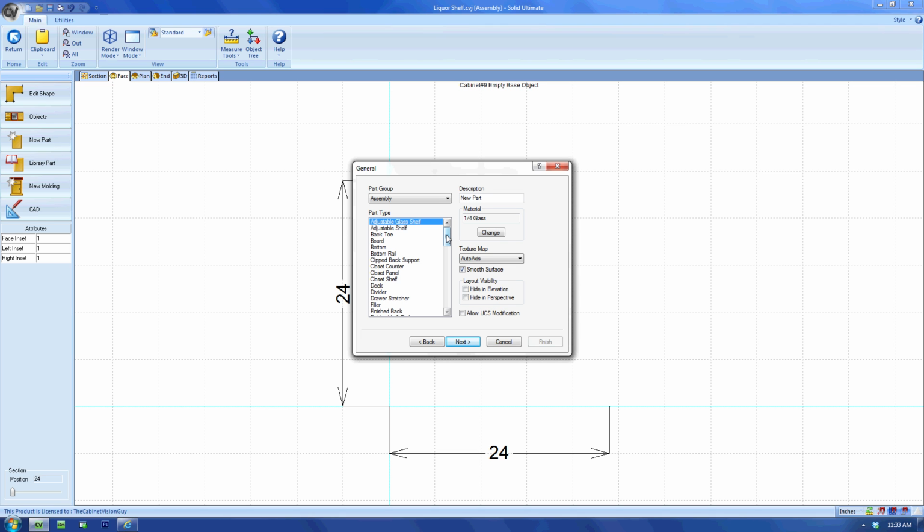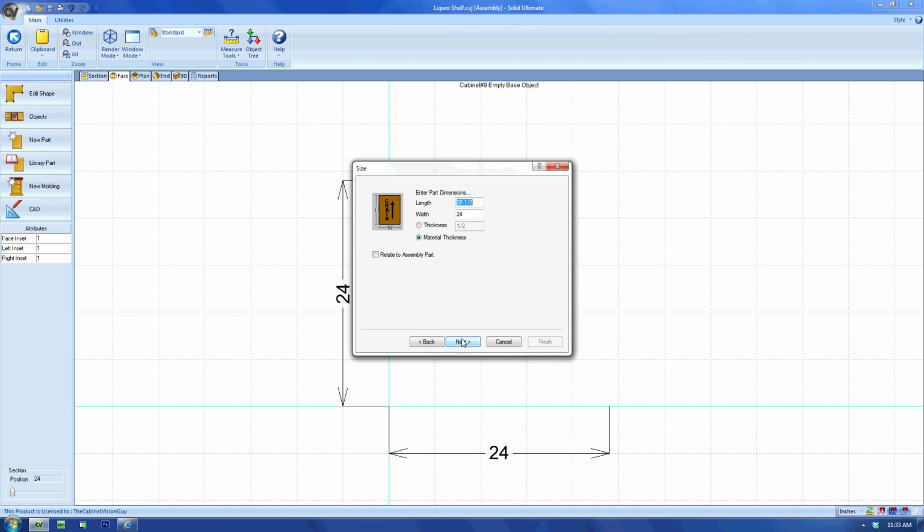So I want to create a top skin. Well, there isn't a skin top part, so I will just use the same part as the skin left finished end. At this point, I would typically stop what I'm doing, go to the part catalog, and create my own new part. Unfortunately, that's a lot of work for this right now, as I would have to go to my material schedules and make sure that each schedule has a material assigned for the part. So yeah, just going to use the skin left finished end. I will, however, rename this part for my guys in the shop to know where it goes. Everything else I want to leave the same, so I can just click Next.